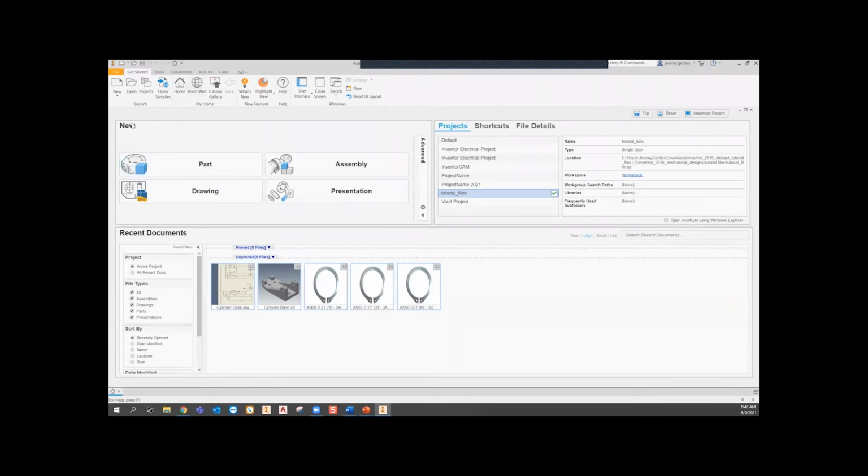Okay, so in this box here, we have new parts, drawings that we can one-click start. So you have part files. This is the backbone and the most commonly made thing in Inventor. It's an IPT file. It is your basic, single part that you created.